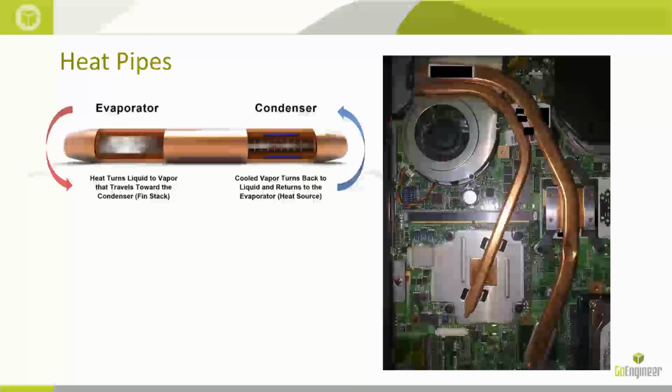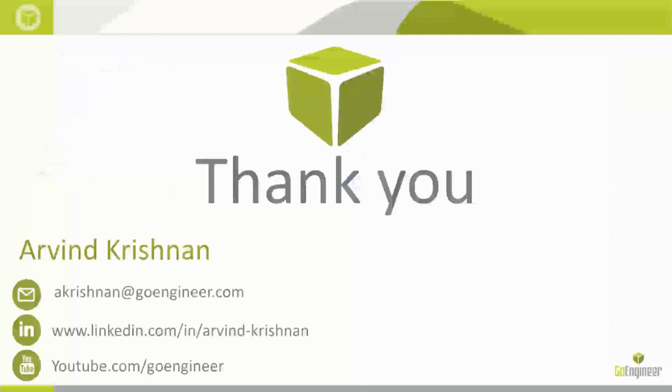So once again, just to sum up the entire analysis, we quickly simulated 11 different designs and compared them, for an electronics enclosure. What we did was we looked at the different thermal distributions, we looked at the different outputs available to us, and we went from there.